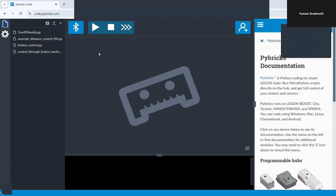PID stands for Proportional Integral Derivative Control. It's a method used in control systems, like robots, motors, and stuff, to make something reach and stay at a desired value, called the target angle or the target distance or the set point. For example, if you're controlling a motor to spin at 100 RPM, a PID controller automatically adjusts the power to the motor so that it smoothly reaches 100 RPM and stays there.